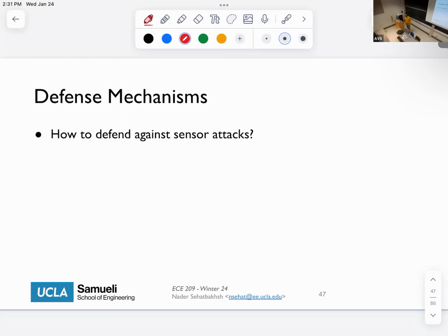So for example, if I have a gyroscope that has a much higher resonant frequency, then it would be very hard for the attacker to create that frequency, or it requires much more range in order to successfully attack the system. Or for the IR sensor, if I have a much extended period of linear behavior, then it's very hard for the adversary to launch an attack, right?